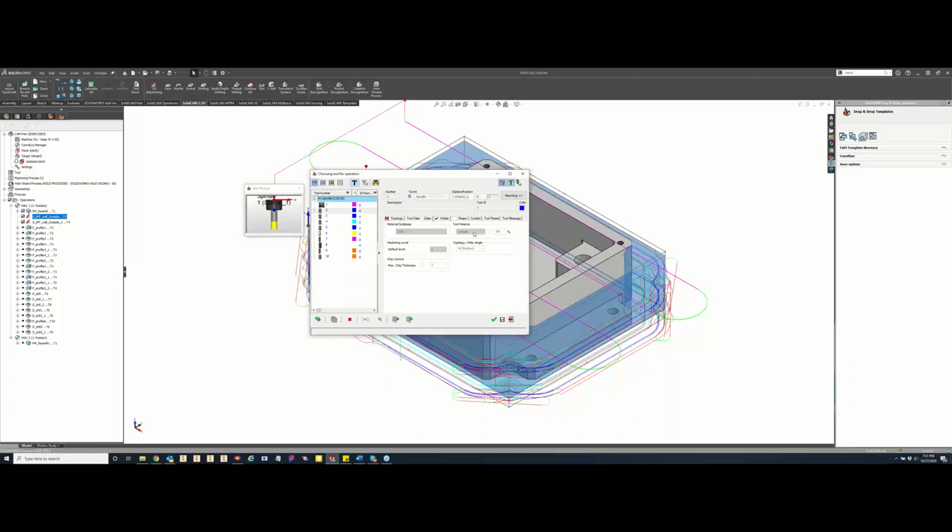So if we're running a carbide end mill, or a coated carbide end mill, that would be a premium. There's cobalt and high-speed steel in there, as well as the helix angle. Now when you get into the softer materials, helix angle isn't as important as when we're running, you know, Inconel or titanium and stuff like that.